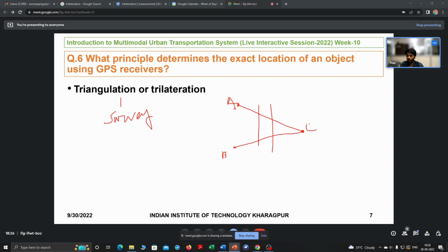Now you know the angle of this and the angle of this. So if you know the angles, then you know the AC distance, you know the BC distance, so everything is known. Although you have a river, just from point A, by using a theodolite survey, you know the angles, maybe vertical, maybe horizontal, whatever it is, then you know the angle.